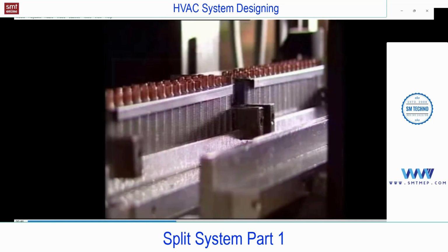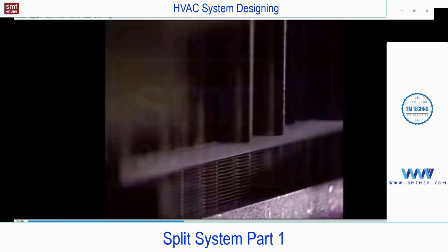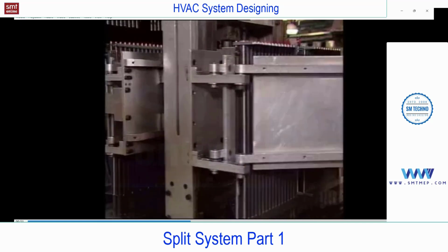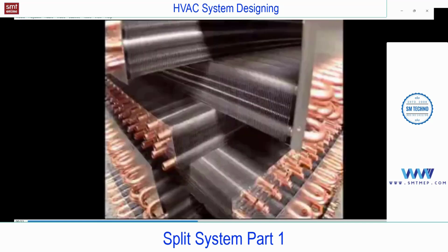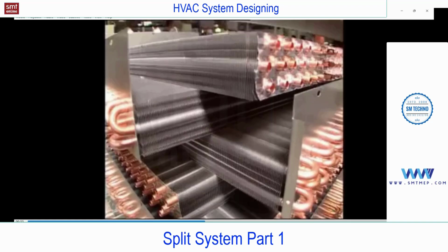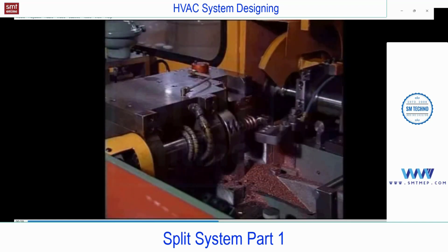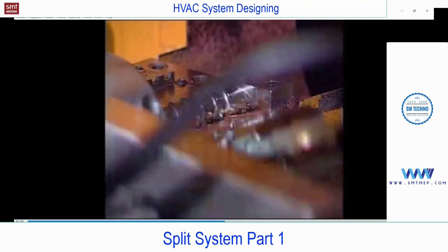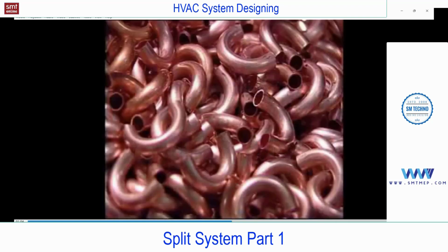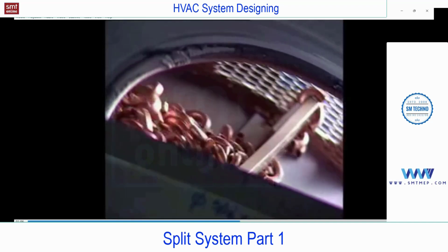Heat exchanger coils are then moved to the mechanical tube expander, where mandrels are inserted into each tube, which mechanically bonds the hairpin tube to the aluminium fins. The return bend machine fabricates copper return bends, or elbows, from copper reels, and then the brazing rings are inserted mechanically.